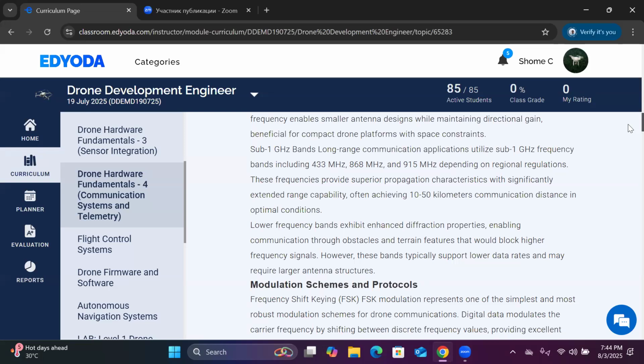No, 5.8 gigahertz is a separate frequency band. 2.4 has nothing to do with 5.8. The 5.8 spectrum is separate, 2.4 gigahertz is separate. 2.4 basically comes under the L band. So under the L band, what frequency you are using, you cannot compare with the sub 6 gigahertz band, because the modulation format, the data transmission capability, the bandwidth significance, the circuitry, the different kind of filtering mechanisms will automatically change compared to that of the 5.8.